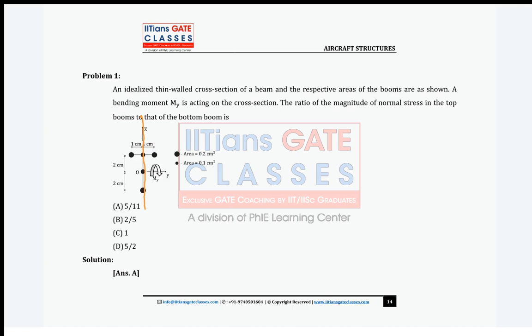Okay. So that means your Ixy is 0. So when Ixy is 0, and what is your moment given? Given moment here, what is your Mz? Mz is 0, right? So that means what? It's a simple bending, right? So that means your sigma x will be what, guys? Your sigma x will be My upon Iyy into z.